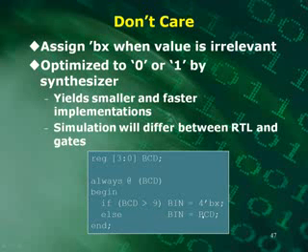So when it's from 0 to 9, bin is going to be equal to BCD. If it's something greater than 9, I don't care. So in simulation, you're going to see 4'bx. But in the actual gate level, if you were to simulate the gate level after it's synthesized, you're not going to see X's. You're going to actually see different values of 1s and 0s, whatever the synthesis tool came up with. And it's going to come up with different values based on the best optimization it can do for this code. So there'll be real 1s and 0s, but you won't really care since it's greater than 9.